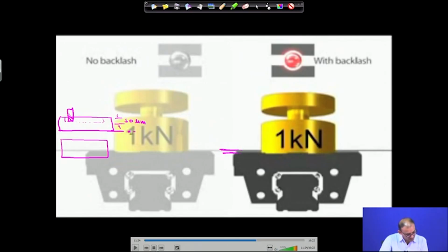So, this is the 0 position, and when you are going to do this, there is a deflection going down a little bit. Consider that the deflection is 10 micron, so this is minus 10 micron down. Your tool is still here, and you assume that your tool has gone 50 micron from the workpiece top surface, correct, but your top surface has shifted down here. This is what you actually want to cut, but because of this deflection, what you are cutting is this one, right. So, you are getting a dimension difference of 10 micron.